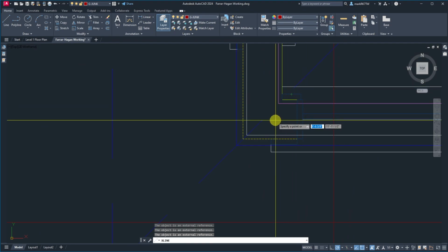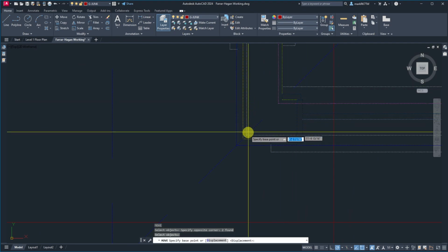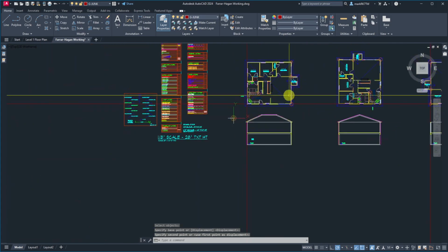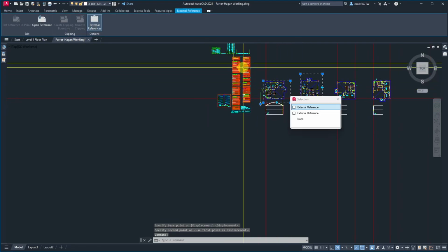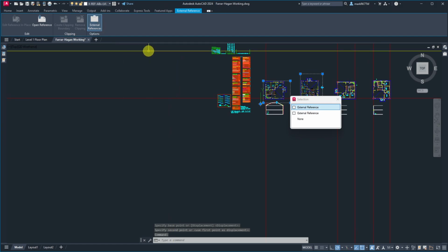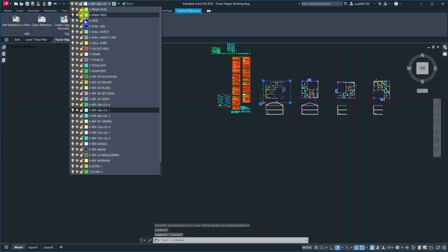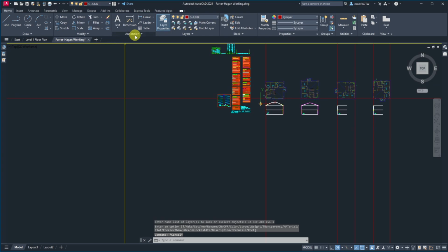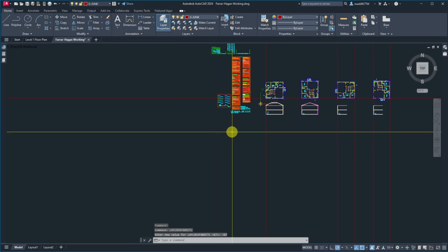So now I can just escape, move that from there to there. Try not to erase it. You can lock this layer, and in my locking, it fades it. So in this particular drawing, I could come in and say, hey, no layer fading in this.